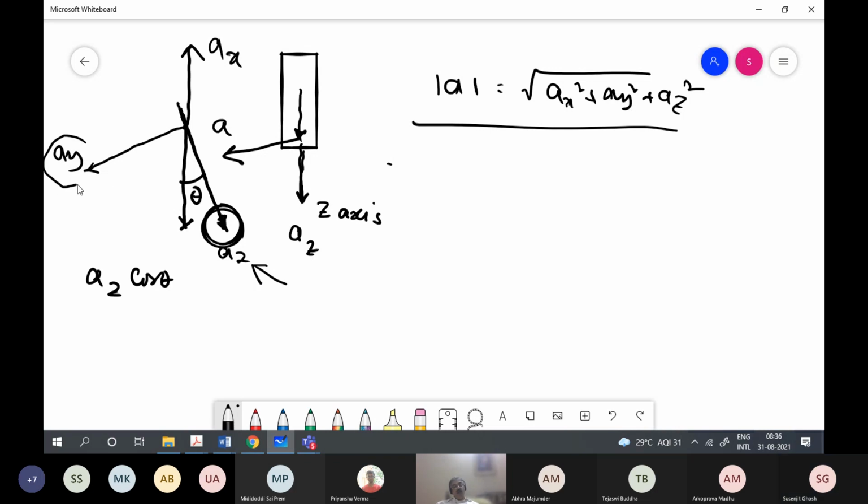The other two outputs are also being produced due to cross-axis sensitivity, but they are not used. Because I am assuming that the acceleration that I am trying to measure is supposed to be aligned with the z-axis. So I am only interested in AZ. So is this clear now?